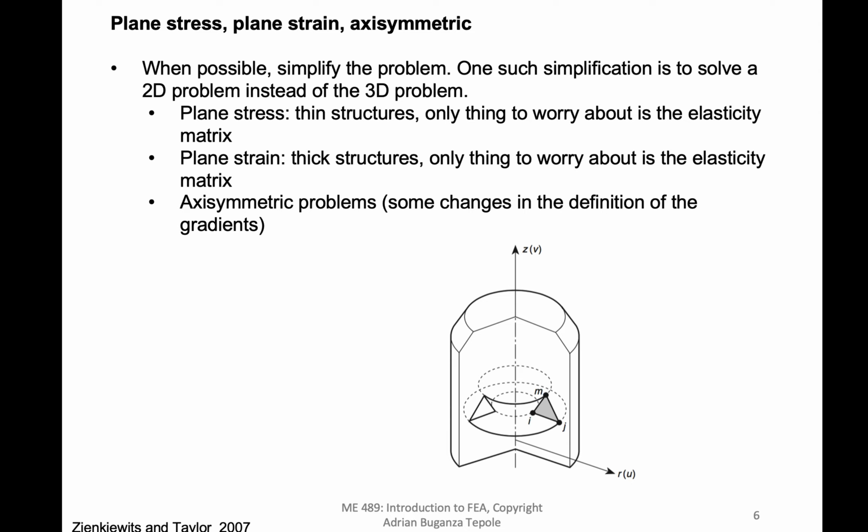Another recommendation, and we have talked about this, is that for your project, for example, you might have a 3D part that you are interested in, and you might want to solve the stress analysis problem with the 3D geometry, but that takes a lot of time, especially if you want an accurate solution. We have done a little bit of mesh convergence analysis, and as you refine the mesh, you get a better solution.